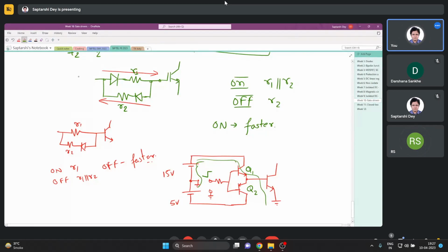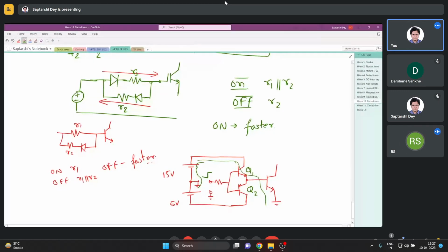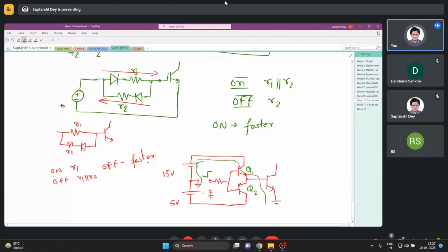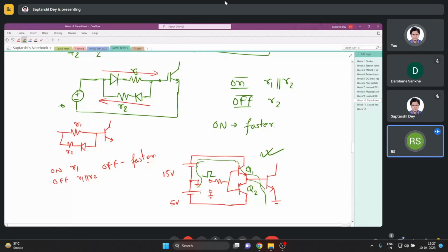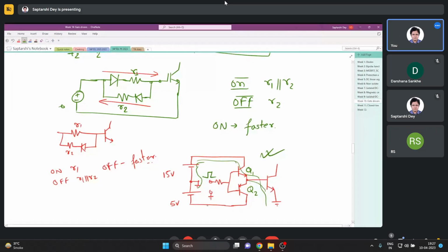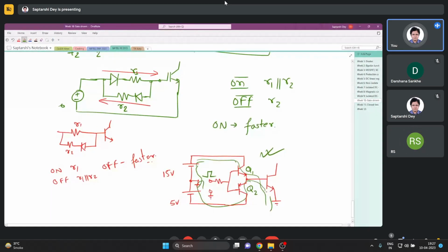Now, in the previous circuit, if you look, your turn off voltage is 0. But in this totem pole, there is a possibility of having a turn off voltage of negative, because when you are keeping it low, the current is flowing like this, through Q2. So the turn off voltage is minus 5 volt now, so the charges are drained out even faster. But if you do not have a fast turn off requirement, you need not make this circuit.